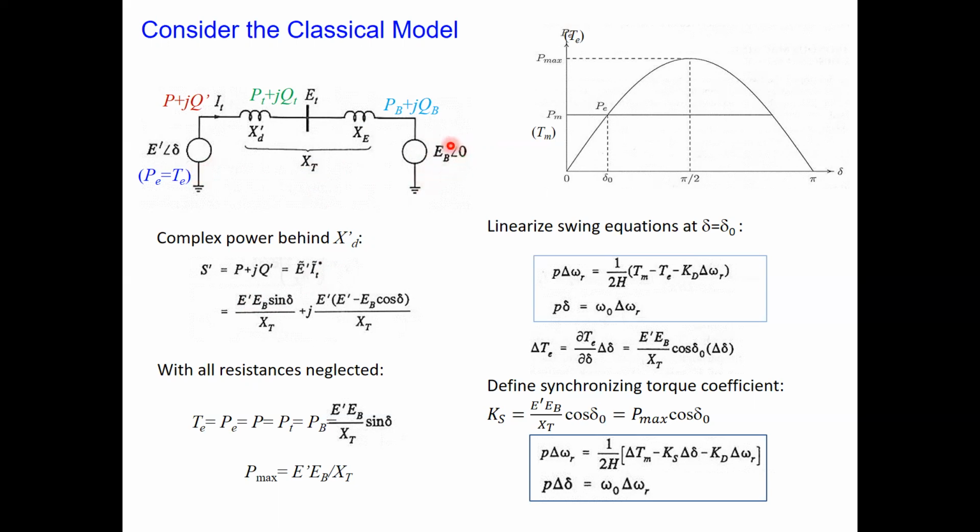So if you remember, for the infinite bus, we have considered this is your voltage quantity, the voltage at the infinite bus here. It is this one. And the angle we have considered as your reference. And then the angle which you have on the generator is delta here. And then these two reactances we have summed here. So writing it in terms of active power and reactive power, it is this way.